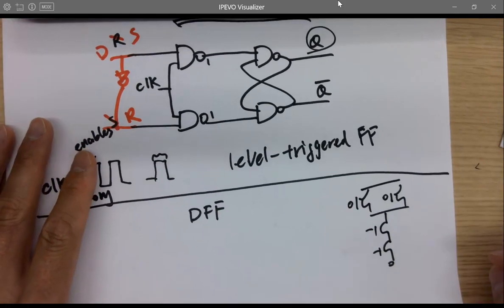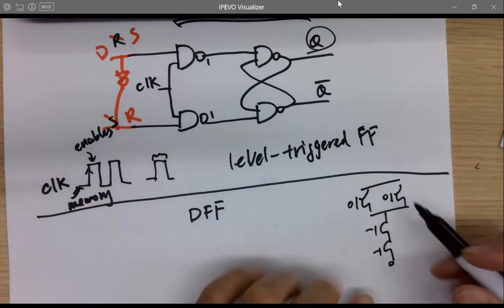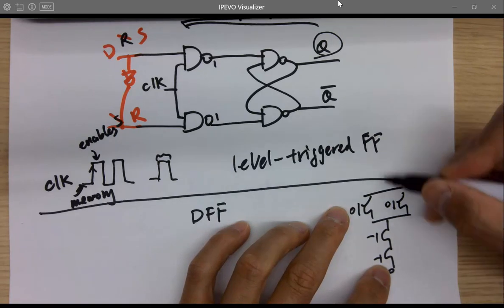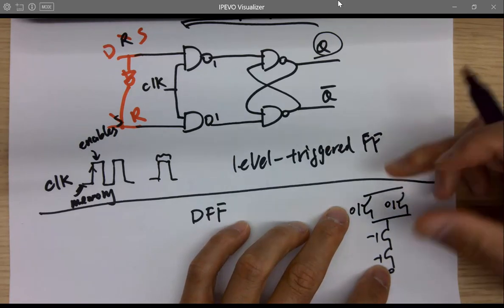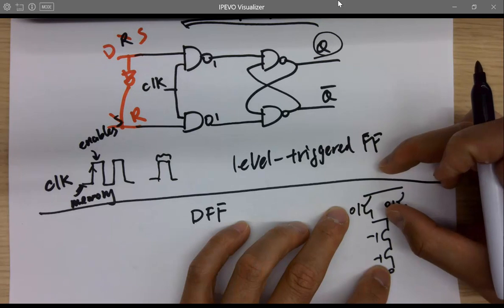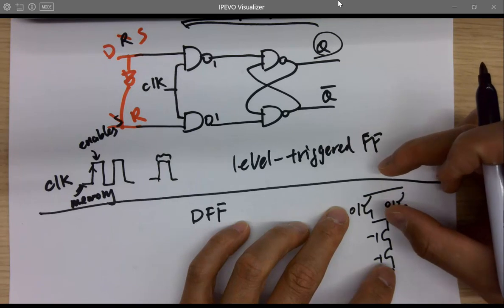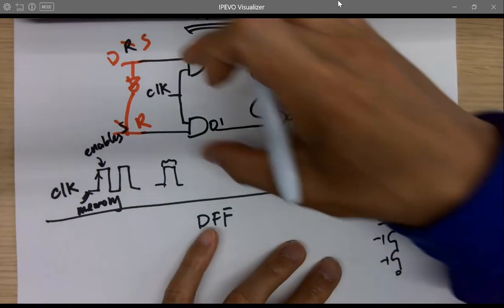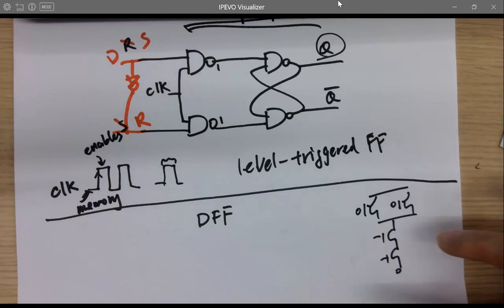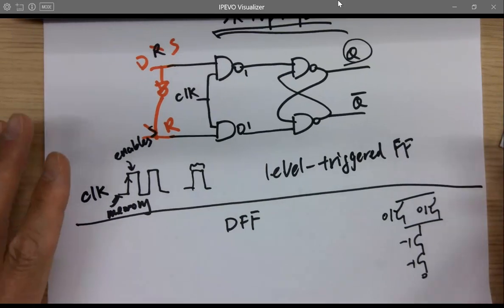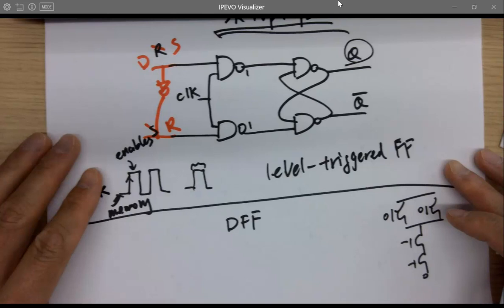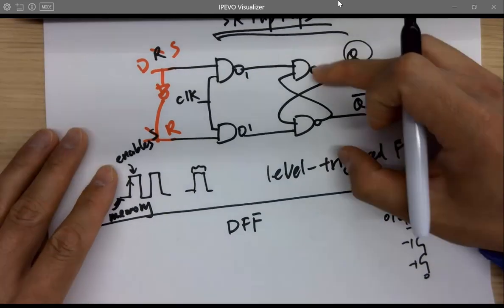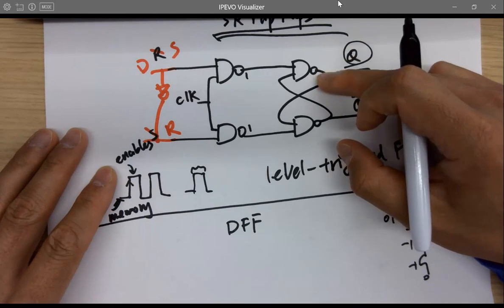I think it's adding, because PMOSes are slower than NMOSes, and if you put the two PMOSes in series on the top, it's adding a lot of resistance to the PMOSes, making it even slower. I don't know if that's the reason for that, I forgot, but you need to know that a lot of times we prefer NAND gate. And you can just build a digital circuit using only NAND gates, instead of any other circuits, because you can use NAND gate to make everything. Yeah, faster than NOR gate, yes.